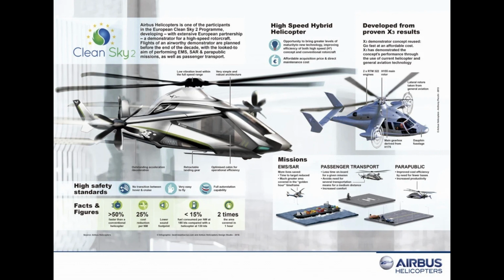Piston-powered helicopters use a heat exchanger shroud around the exhaust manifold to provide cabin heat. Outside air is piped to the shroud and the hot exhaust manifold heats the air, which is then blown into the cockpit. This warm air is heated by the exhaust manifold but is not exhaust gas.